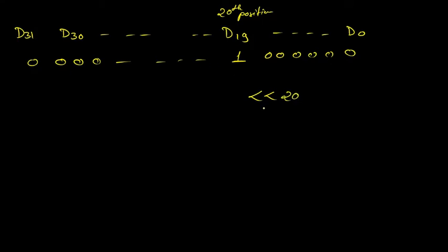So it is much easier rather than decoding what the number is and how to put that number in that register. Simply go to that 19th position or 20th position and write that 1 there. That's all. So this is bitwise manipulation. We can use left shift operation to introduce 1 in a particular position of the register.